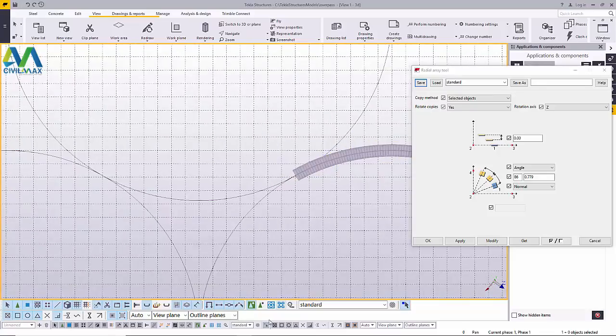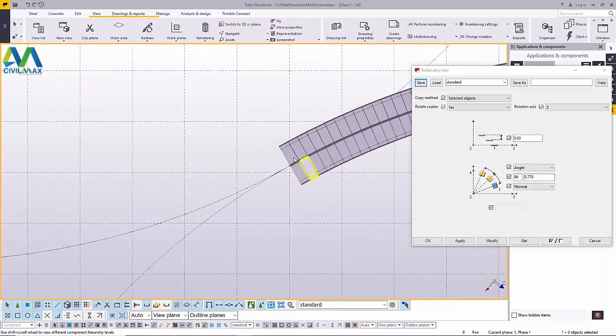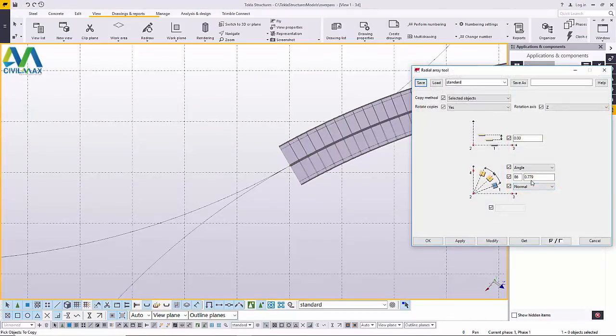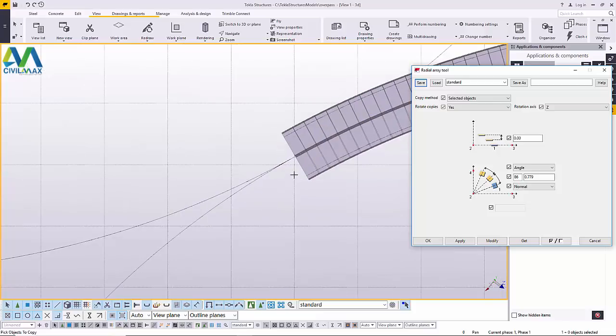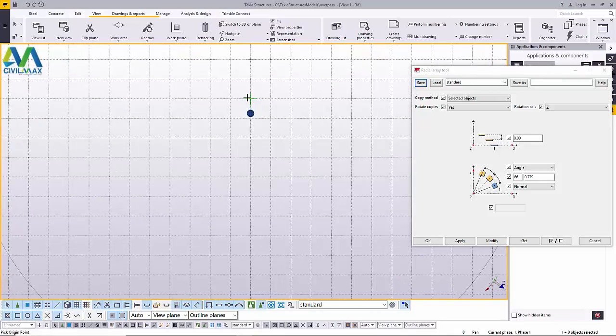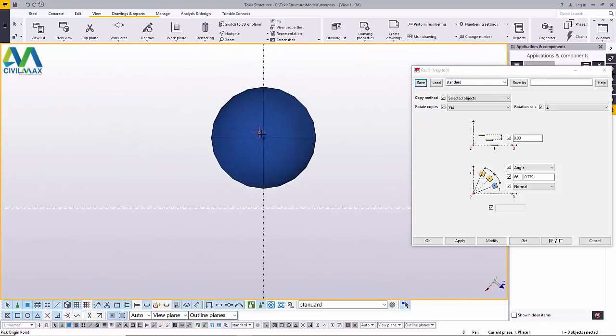Now what do we do? We will deactivate the assembly, and now come here and pick on this. You can pick on the two, close this and activate it once again, and pick on these two parts. Pick on that, press Ctrl and select on that, press Ctrl, press the middle button of the mouse, and now we are targeting the midpoint at this end.